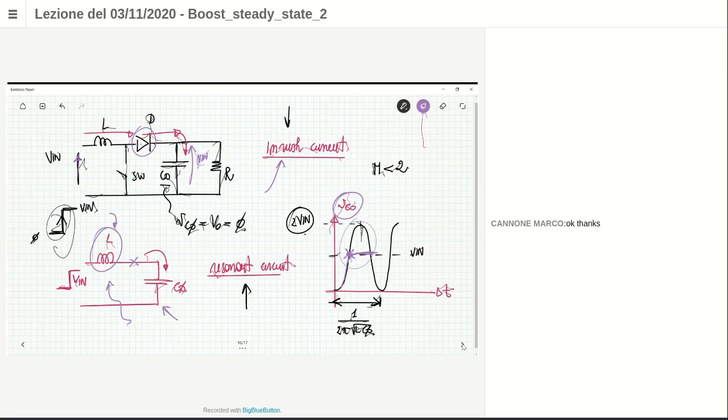I don't want this inductance to get into saturation, so I don't want it to become a short circuit, because I want to avoid the inrush current becoming higher. So I need to put a resistor to damp out this oscillation. You can put a resistor here, you can put a resistor anywhere.